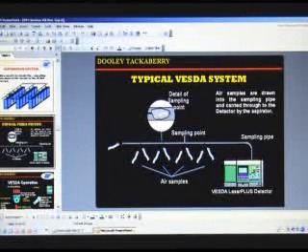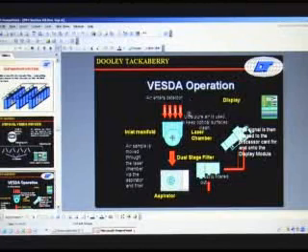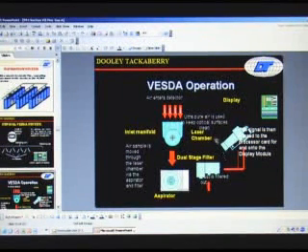The air is drawn into the sampling pipe and carried to be detected by the aspirator. Here's a slide showing how the aspirator works. The aspirator has a fan and a filtration system, and it has a detector. So it detects and sends a signal that there's something wrong with the air. Then they shut down or do whatever they have to do to control the problem.